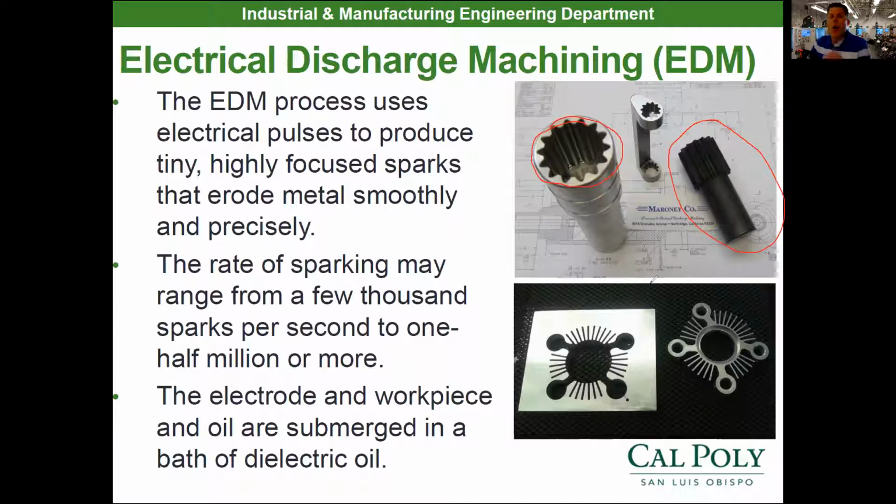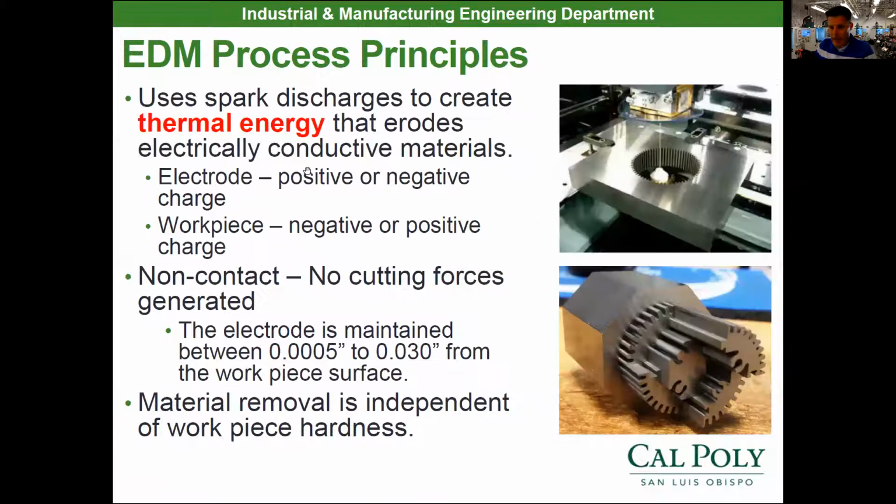Now, in the wire EDM form, that's right down here, it uses a metal wire. It's like down to 2 thou, 1 thou thick wire, depends on what thickness of wire you get. But it can go ahead and cut out the material out of metal with that wire now. So it's a lot like a hot wire through styrofoam, if anybody's ever done that to cut styrofoam out. But with this EDM, remember there's two versions of that process, right? So there's sinker die and wire.